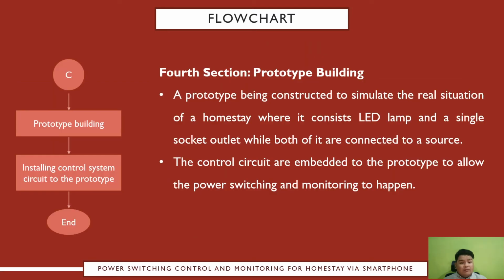And this is the fourth section of my flowchart, focusing on my prototype building, where a prototype is constructed to simulate a real situation of a homestay. That real situation of the homestay, I represent using an LED lamp and also a single socket outlet, where both are connected to the source, but the live wire for both appliances is disconnected and connected to the 2-channel relay module for the switching operation to be performed.